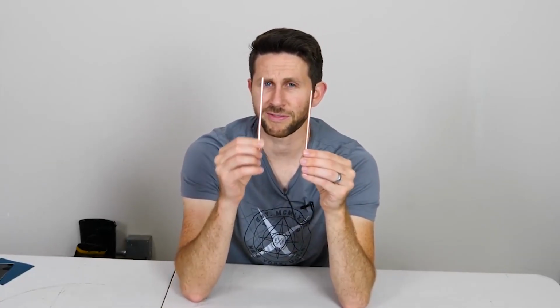I have two rods here. One of these is just a regular copper rod. Now copper has a very high thermal conductivity. It's one of the fastest conducting metals there is. And because electrical conductivity and thermal conductivity are related to each other, that's why you see a lot of wires made out of copper, because it can also transfer electricity easily. So I'll compare this copper rod to this heat pipe here and show you how much faster this heat pipe actually conducts heat compared to this copper rod.